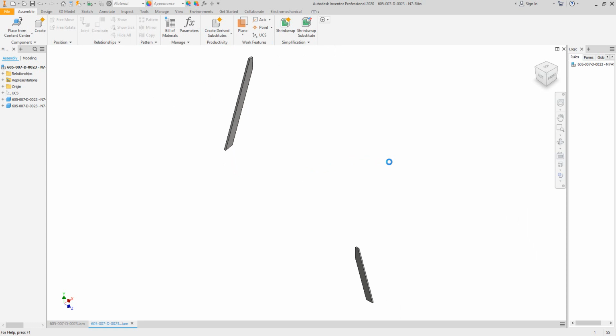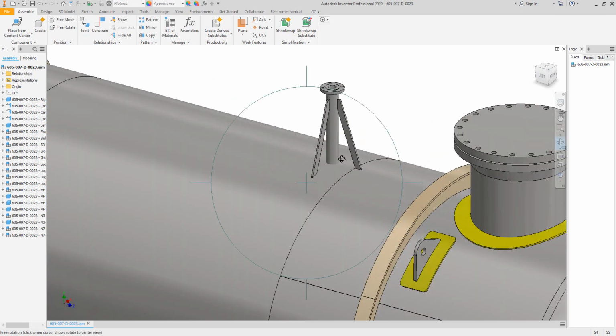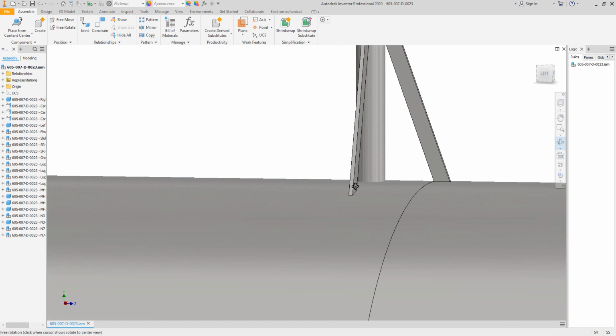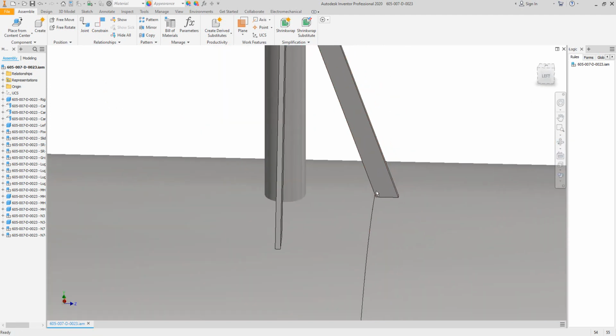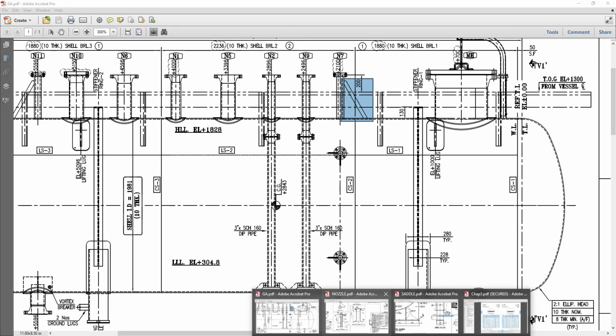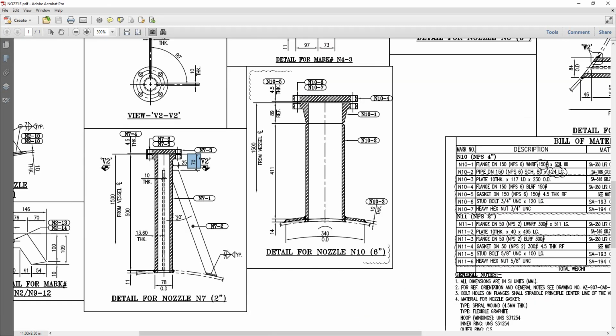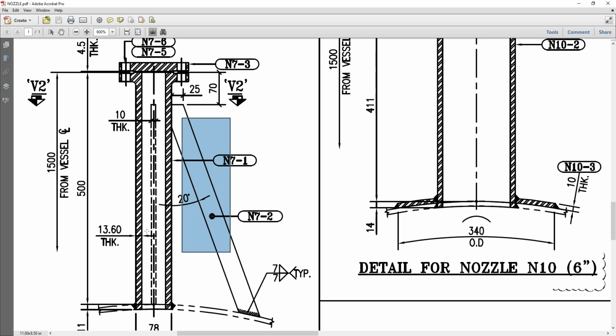That's the first stiffening rib. The second stiffening rib. Okay, so you can figure that you have 2 stiffening ribs here. As you can see, the longitudinal welding line orientation is near to this stiffening rib. And if we take a look at the drawing here, you can figure that it's 20 millimeters for the lateral one, but for the second one is not mentioned.